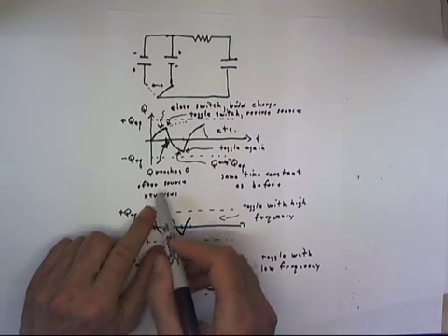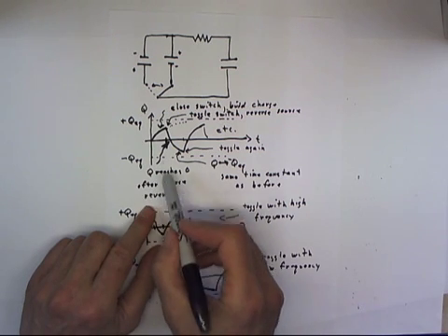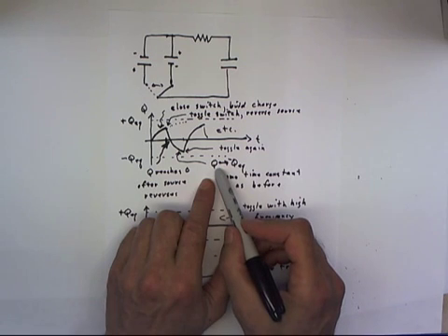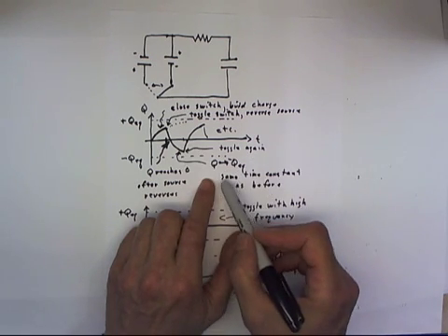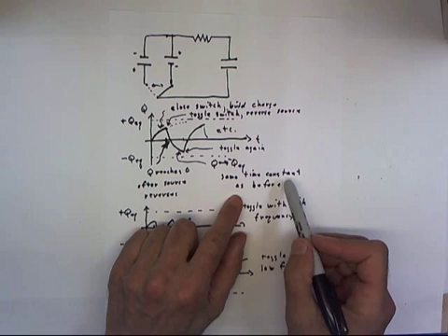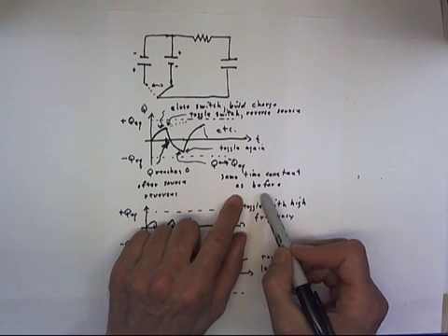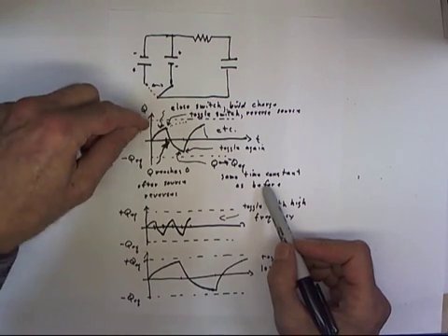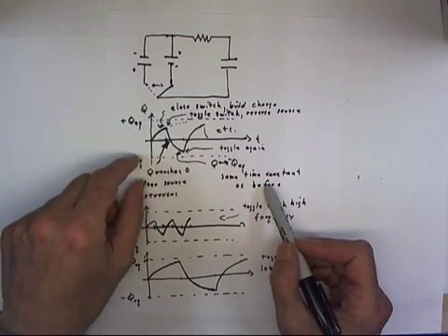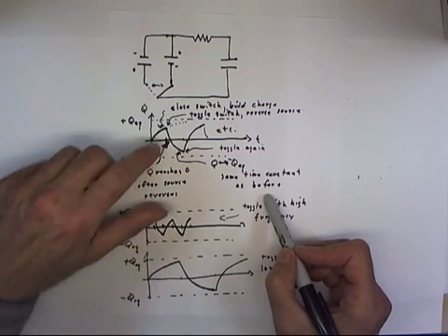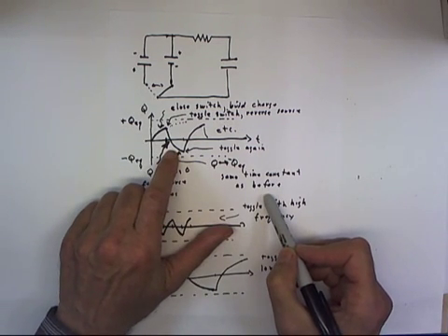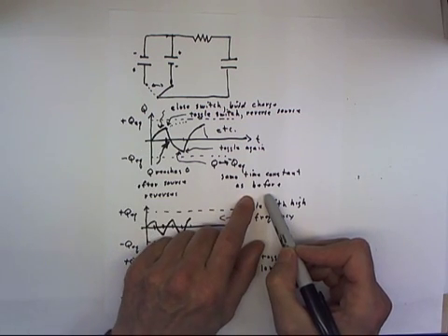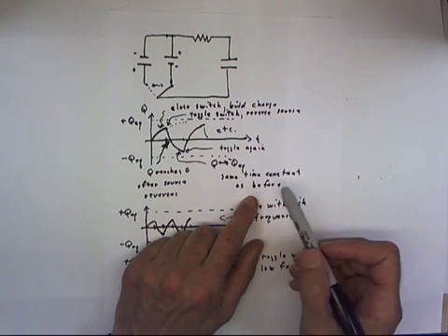So I've made that note that Q reaches zero after the source reverses, and then Q approaches negative Q equilibrium with the same time constant as before. That means that the half-life of our approach to this equilibrium is the same as the half-life of our approach to this equilibrium. I probably didn't do a really good job of drawing it that way. You might think about how you would draw that more accurately to reflect this condition.